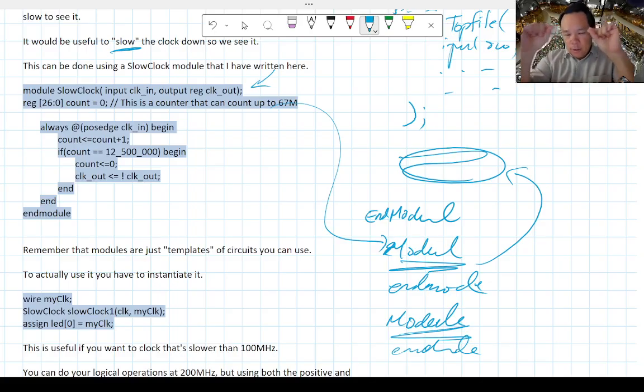And 99.99% of the time, Vivado is able to figure out, okay, I want to run this top file first. Once in a while, it does get confused and tries to, let's say, run your slow clock first. In that case, the code is not going to compile. You're not going to be able to synthesize it. Okay, but then you just have to go back and manually set your top file to be the first module that gets run. Okay, if you were developing things in the order that we do in the lab, it should work out because you always define the top file first, and that's the one it picks.